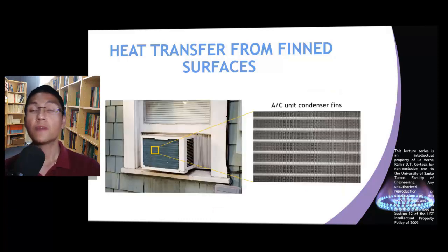You have probably seen a fin surface before without even realizing it. Fins are widely used to increase heat transfer from the condenser tubes of an air conditioning unit. This is the primary purpose of the parallel vertical rectangular plates placed on the surface of the condenser tubes. These plates are called fins.